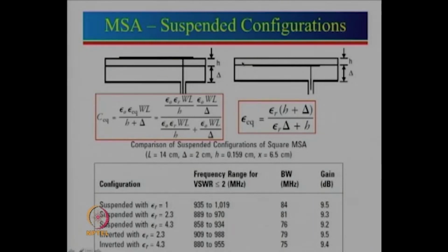So now comes the next part: how do we support these antennas? And if this has a good thing, then why use this one here? First of all, the major problem with this is, let us say we put a ground plane here and we have put an antenna there, and we need to solder here. So sometimes it becomes very difficult; I have to bring the solder either from the side here and all that.